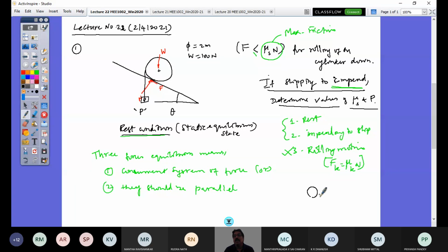A passenger car which is parked, which is not moving, which we have looked at, right? If we take this car, the weight is acting down and the support reactions at both the wheels are there. This is its free body diagram. So this is front axle load and this is rear axle load and this is W. Look, these three are a parallel force system.